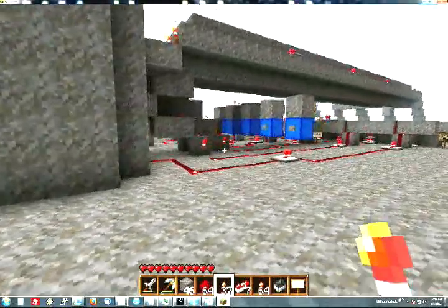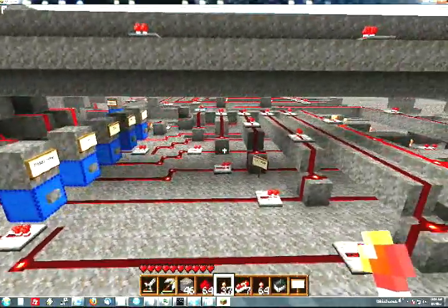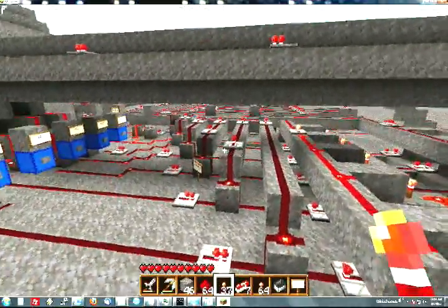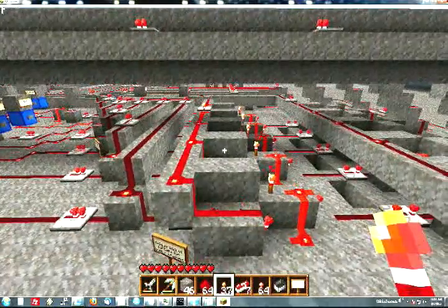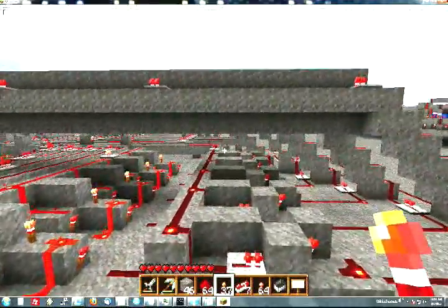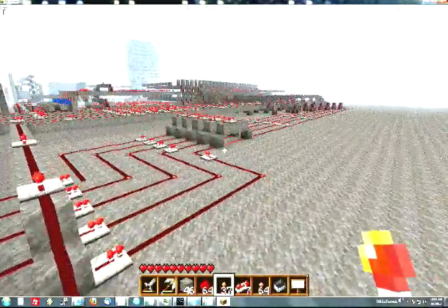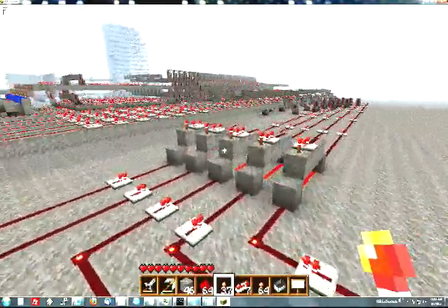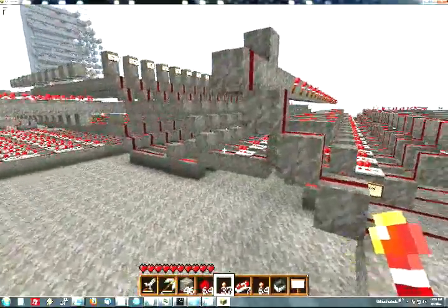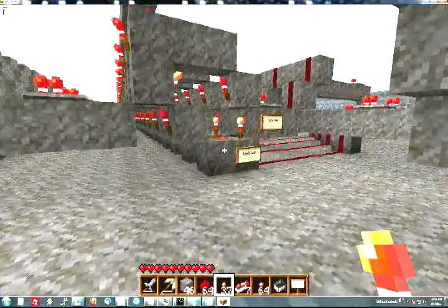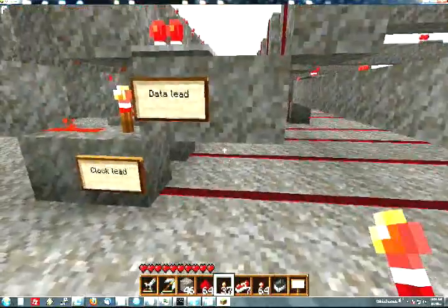So let's check out the electronics. These are the clock leads. There's several different things the clock needs to do each time a button's pressed. These are the fail-safe AND gates. These are latches that hold the current state of the system. So all that basically just turns the buttons into self-canceling levers. These are pulse generators that generate the main pulse for the system. These are delays that help with the memory of remembering the prior state. These are the heart of this, the activity selection: these D flip-flops with the data and clock leads.